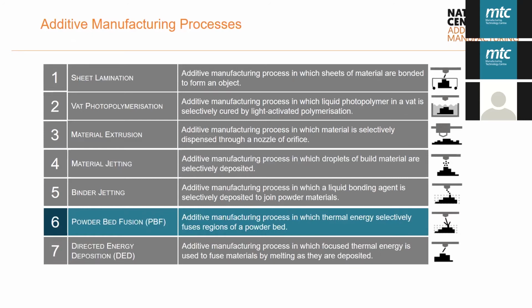So how can metal binder jetting be used for manufacturing an orthopedic implant from, is it Ti6Al4V? Yeah, so Ti64. Using Ti64 material in metal binder jetting or any indirect additive process, as far as I know, is quite difficult, mainly because of potential oxidation of that material.